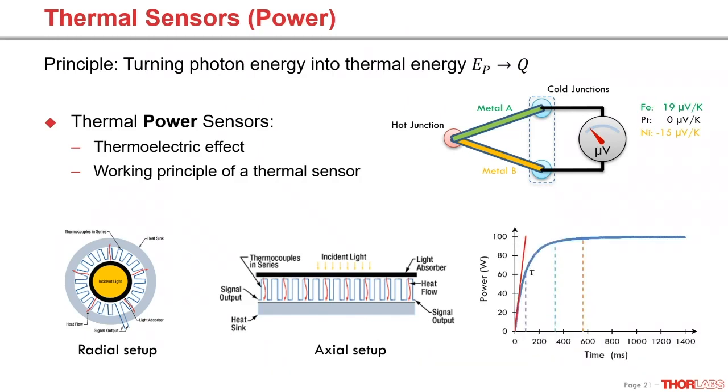The thermal sensors respond in an exponential function, like charging a capacitor. The key parameter here is the time constant. This is the time when 63% of the final value has been reached. That time constant characterizes the response speed and is also used to perform a measurement prediction, allowing the display of the power prior to the voltage having finally settled.